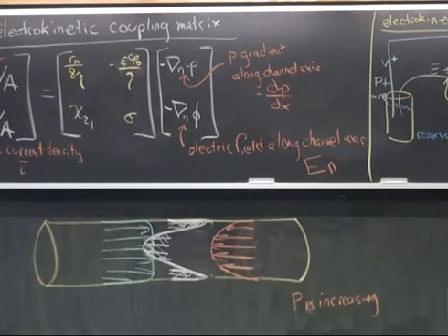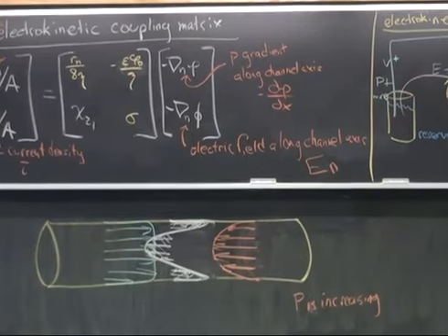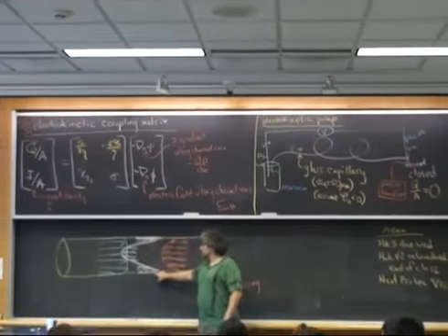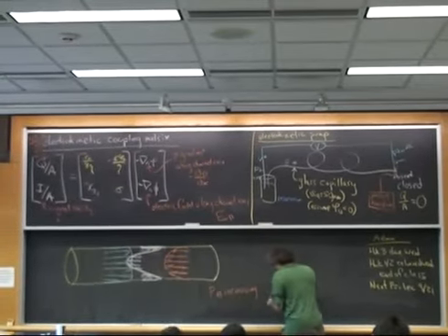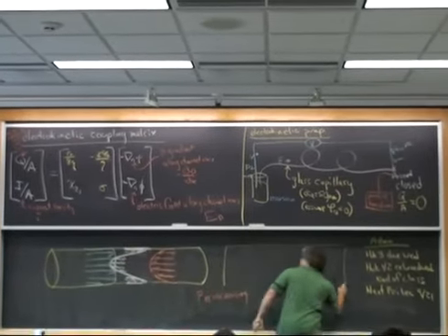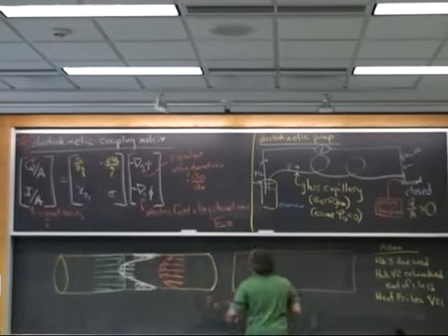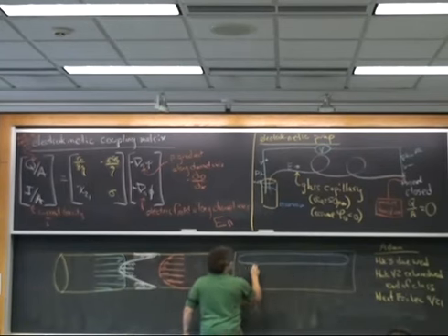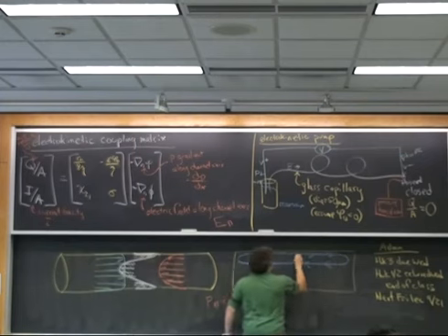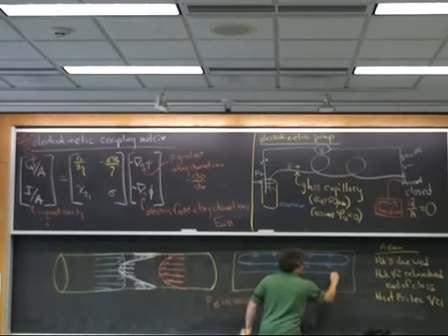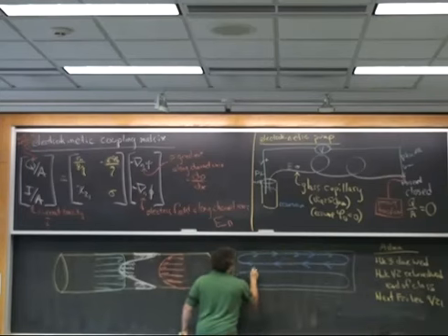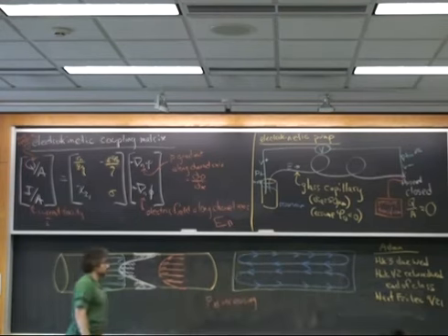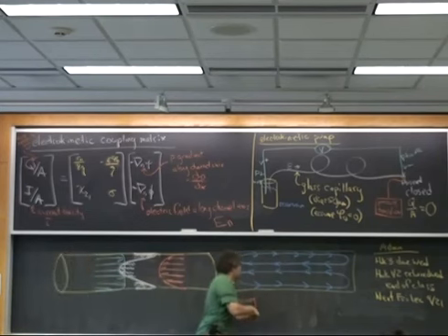So in fact, if I take this glass capillary and I apply this voltage, several different things happen. I build up a pressure at the outlet, which I can measure at my pressure transducer. I generate a flow that moves forward near the boundaries, but moves backwards in the center. And in fact, if I extend out the streamlines of this system all the way from the inlet to the outlet, my streamlines all look like this, here in the center of this tube.